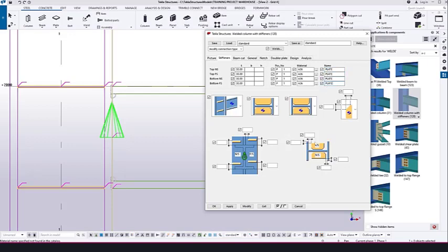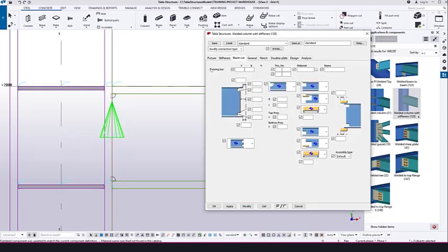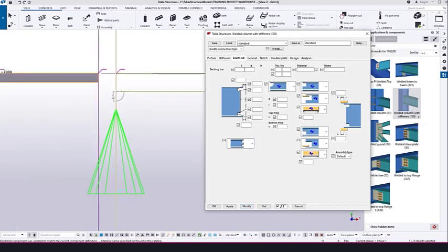For the stiffener, if you need any other things, you can make that also, like edge distance, or if you need to arrange, everything is possible, but just keep as it is, simply modify. Here it is placed. Then if you go to the beam cut, you can see if you select this one, you will get a cut like this, and if you made it like this, you will get it flush. But I need this one, so I just make it this one, and here it is modified. If you want the dimensions and all, you can decide here, otherwise just keep as it is.